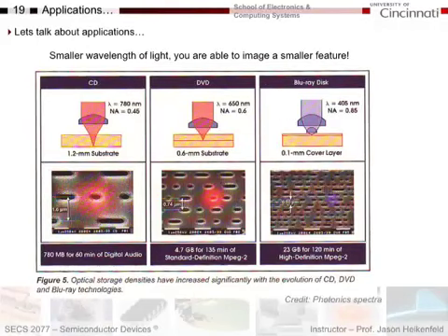Okay, let's wrap up lasers with some applications. Some of the applications, which are no longer as popular now, are CD, DVD, and Blu-ray. When they record data off these discs, they shine laser spots onto pits or reflective areas, and whether or not you get reflection, a pit would be no reflection, and a smooth area would be reflection, you get a 1 or a 0 in terms of the digital bit written into the disc.